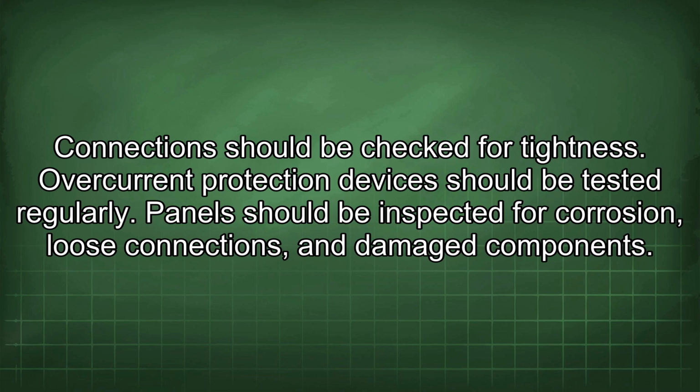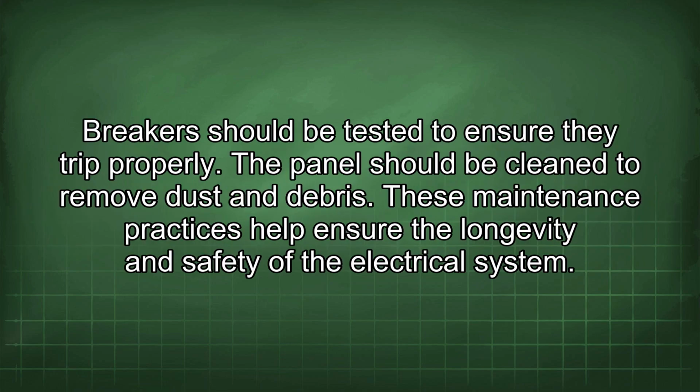Panels should be inspected for corrosion, loose connections, and damaged components. Breakers should be tested to ensure they trip properly. The panel should be cleaned to remove dust and debris. These maintenance practices help ensure the longevity and safety of the electrical system.